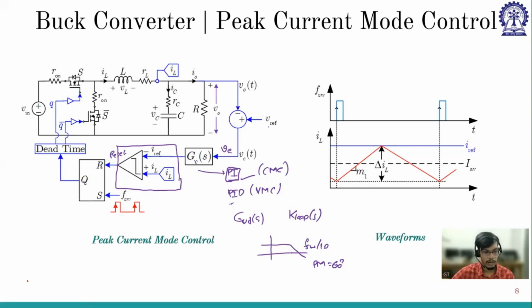So in actual hardware, what happens is you sense this current. This sensor will convert amperes into voltage. Whatever current it sends, it will change into voltage. So maybe the sensor gain Kc will be, say, 1 millivolt per ampere. So for 1 ampere, it will generate 1 millivolt, or maybe 1 volt per ampere. Whatever sensor we are using will convert this current into equivalent voltage.